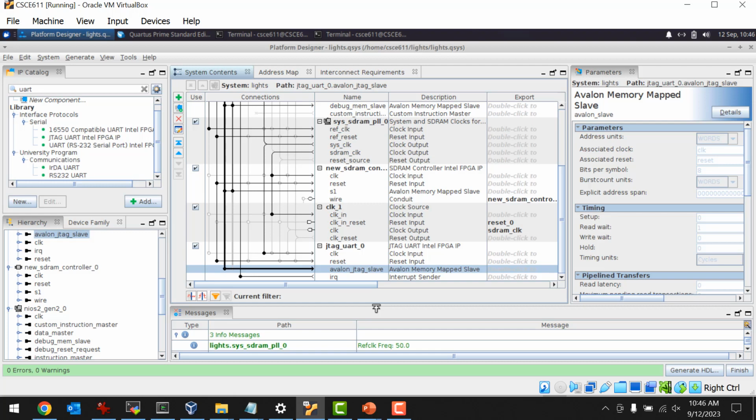But the problem is that all you can pick is individual signals. It would be nice if you could put one of those Signal Tap probes on the Avalon bus. And you can do that easily in Xilinx. You just put an ILA probe in there and you can trigger on bus transactions. How cool would that be? You could actually see the bus transaction.